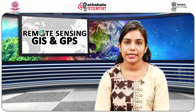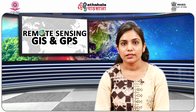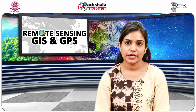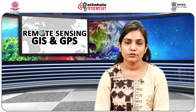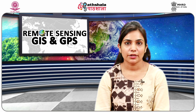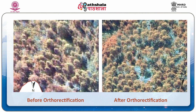An orthophoto is an aerial photograph that has been geometrically corrected, or orthorectified, such that the scale of the photograph is uniform. Orthophotos are photographs that have been corrected for distortion, which is due to tilting of the camera during the photographic survey, distortion from the camera lens, and relief distortions. Orthophotos display all the valuable information of a photograph, but unlike a photograph, true distance, angles and areas can be measured directly. An orthophoto is an accurate representation of the Earth's surface.